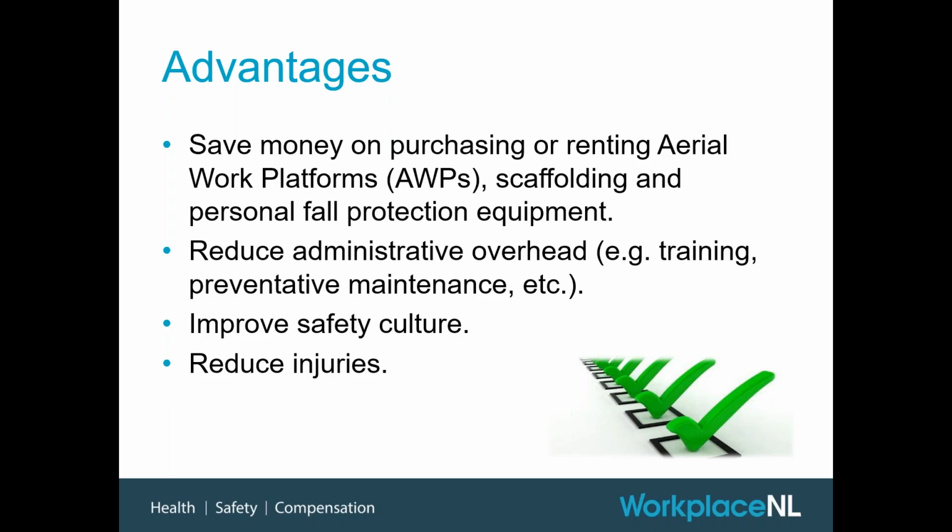Depending on the specific situation, aerial work platforms, scaffolding, and personal fall arrest, all these things require training and preventative maintenance, which can be expensive. Depending on if you own or rent, there can be some variation there. But lifts need regular maintenance. Occasionally they get damaged and they need to be repaired. Scaffolding can be very expensive to rent. It can also be very expensive to purchase. And you need qualified people setting that stuff up, dismantling it, modifying it, etc. There's requirements to check it daily and these sorts of things.